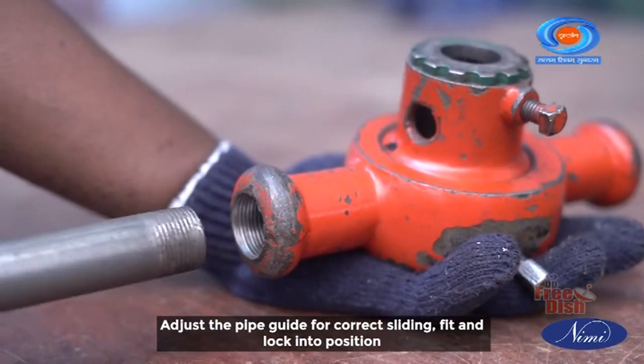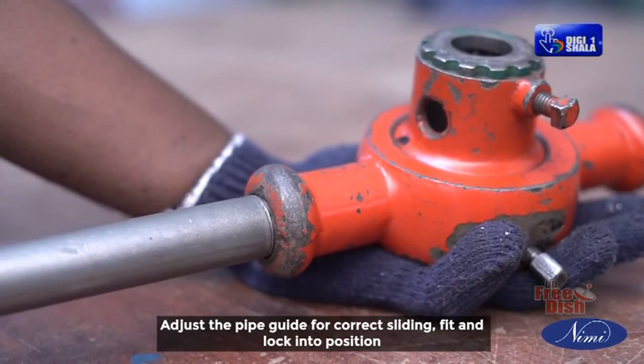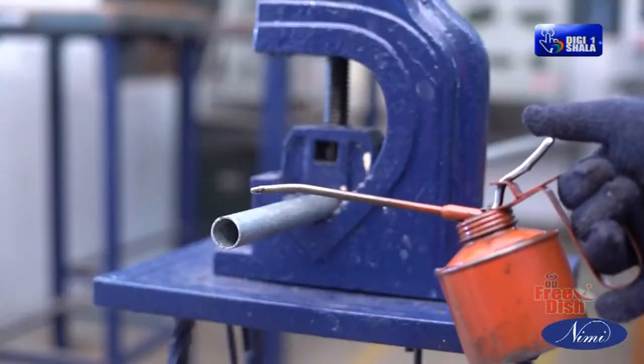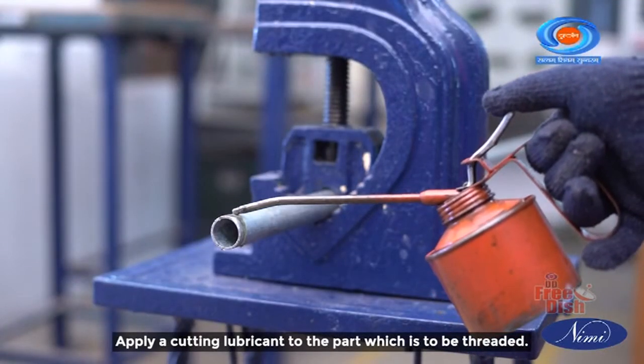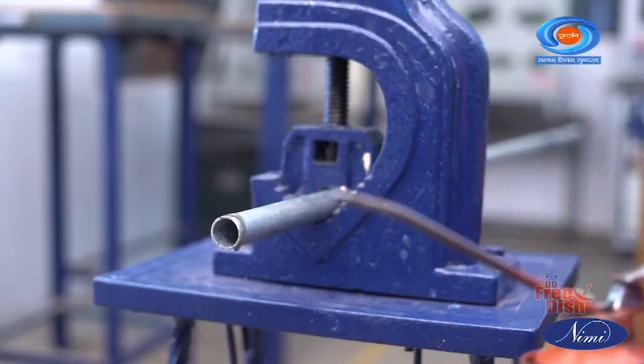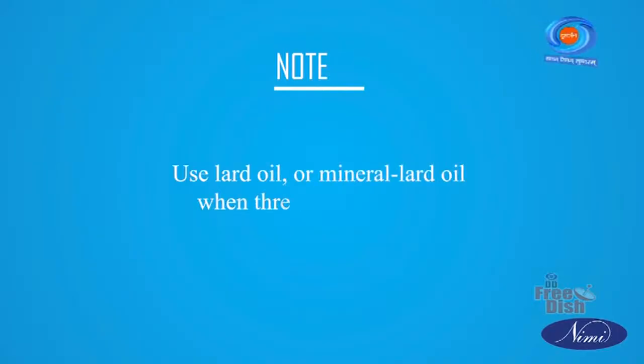Adjust the pipe guide for correct sliding, fit, and lock into position. Apply a cutting lubricant to the part which is to be threaded. Note: use lard oil or mineral lard oil when threading GI pipes.